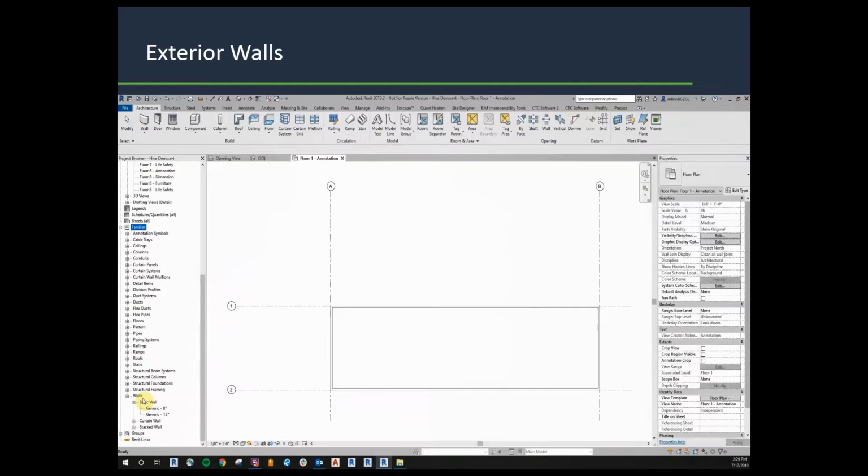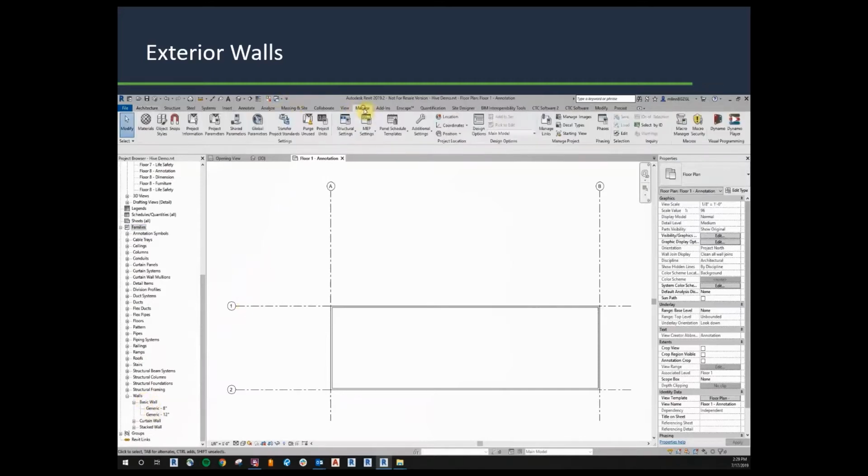We've got a couple of ways that we could solve this. I mean, we could use transfer project standards from another project. So we'd go to manage and click on transfer project standards here. But first, you would have to find another project with that specific wall, and then you would have to go through the process of adding it under manage transfer project standards. And yeah, you saw that I didn't have another project open to grab it from. So Revit just shut me down.